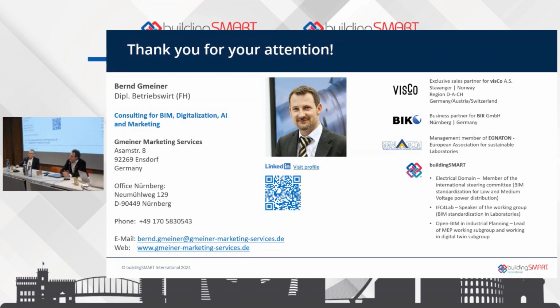Yeah. Okay, that's a good point. What I didn't show in the slides, because maybe they would have been too technical, are the lines you were seeing between these entities, for example, for the IfcElementAssembly towards the IfcDistributionBoard. There are, of course, some relations which already exist in IFC, and they are inverse relations.